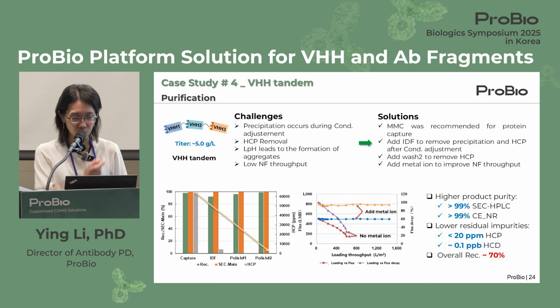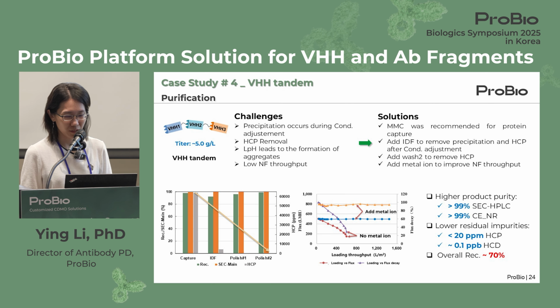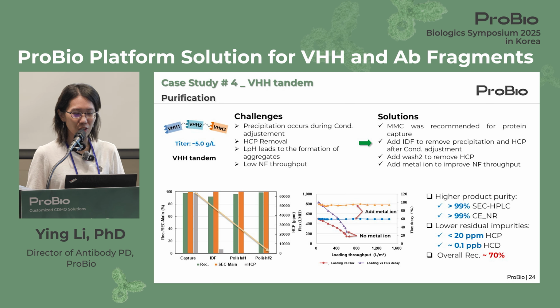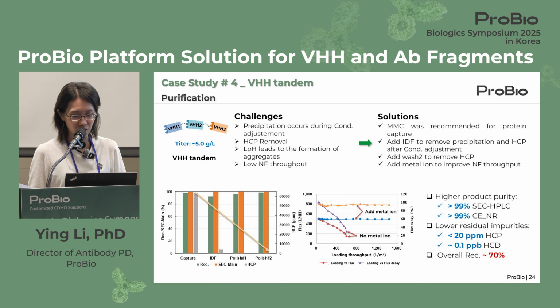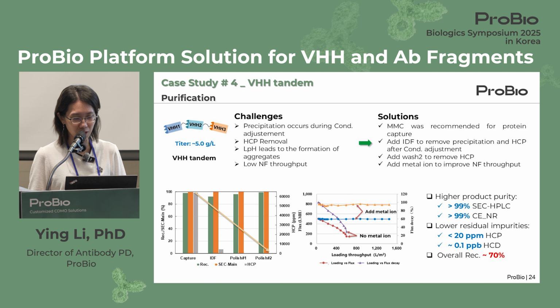temperature. So moving on to the downstream, we see this molecule is not quite stable, so we see precipitation occur during conductivity adjustment when we utilize the mixed mode CEX as the capture step. And additionally, HCP removal has some challenges. So we did a number of things, including adding intermediate depth filtration to remove the precipitated HCP through the conductivity adjustment, and adding wash 2 in the polishing step to remove additional HCP species.